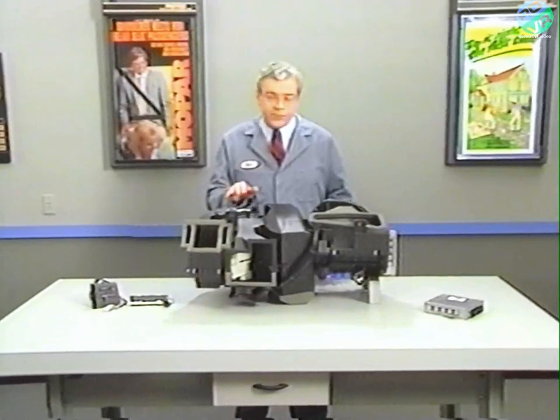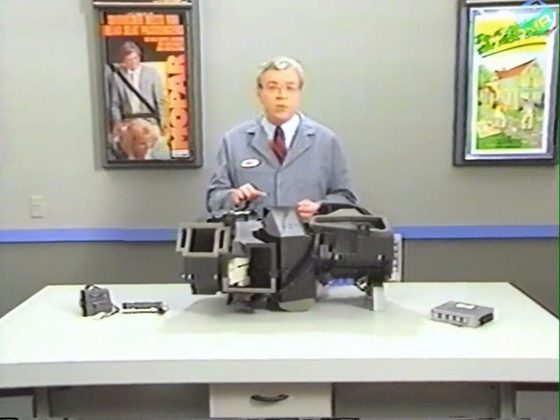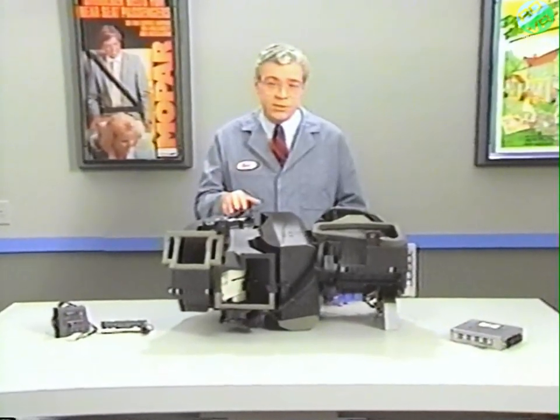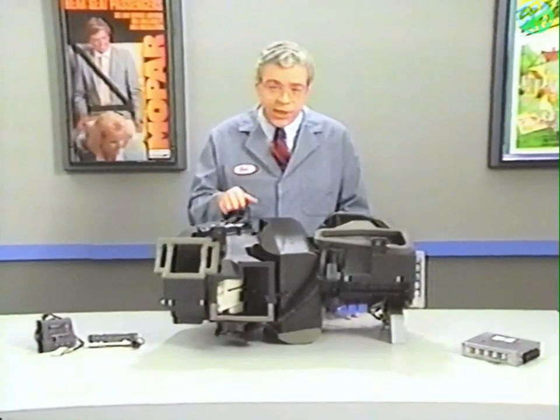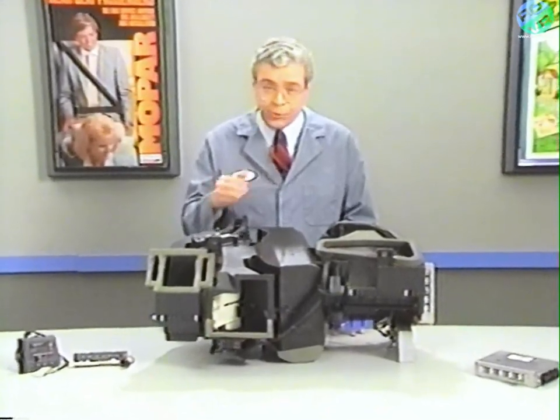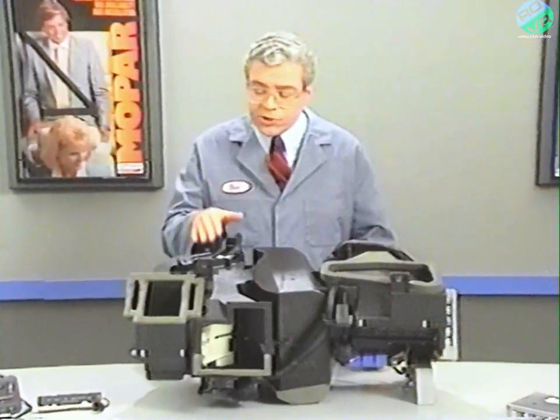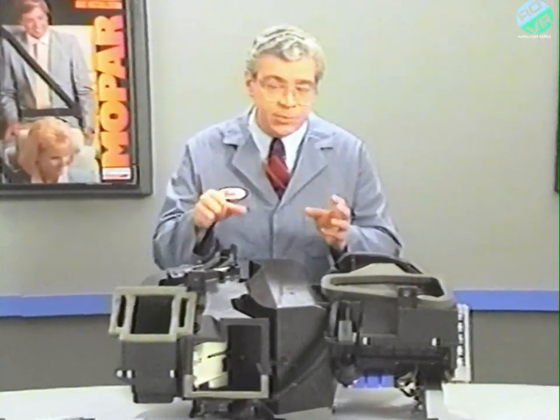This is an important feature of self-diagnostics, since the air mix door motor should not be removed from the plenum for diagnostic purposes. The motor is calibrated to the ACM, and removing it and operating it will cause the system to go out of sync. Because of this, the motor should not be operated unless it is in the plenum.